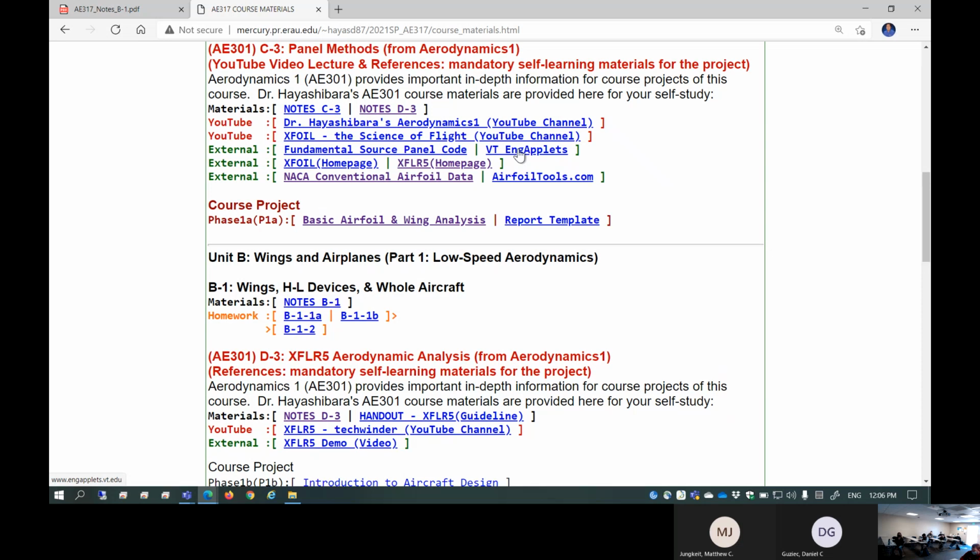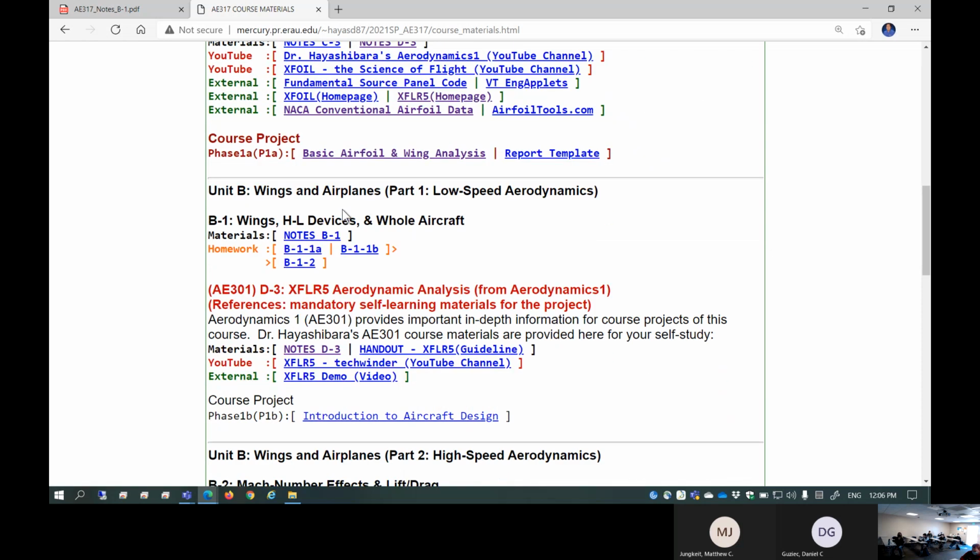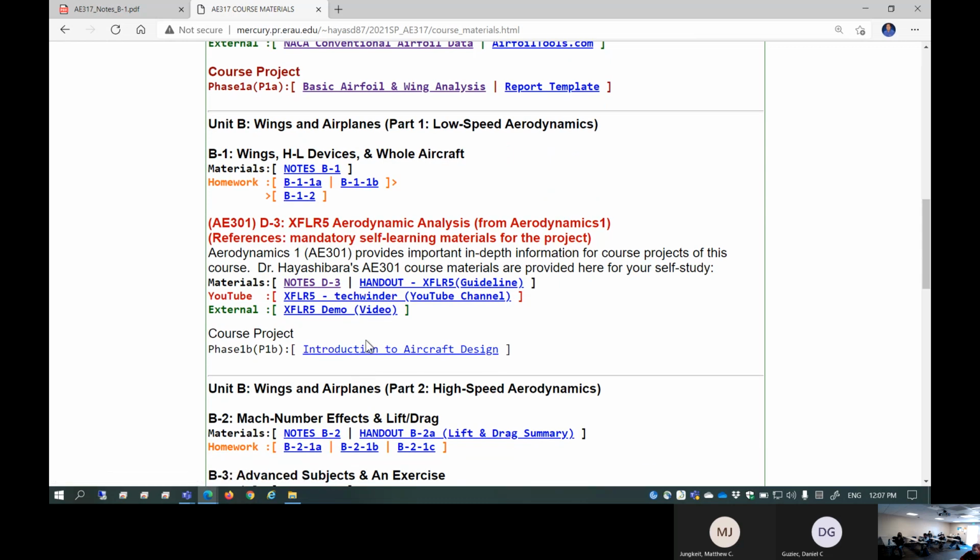Okay? So building the 2D database, something called polar plot, or polar mesh. Sometimes people use those words. Polar. You have to create the polar data. And you have enough polar data database to cover just about any range of Reynolds number and angle of attack of your 3D wing that you're supposed to be designing. Then and only then you can move on. So those are the important things you have to pick up in phase 1A and phase 1B. That's what I'm thinking. Okay?